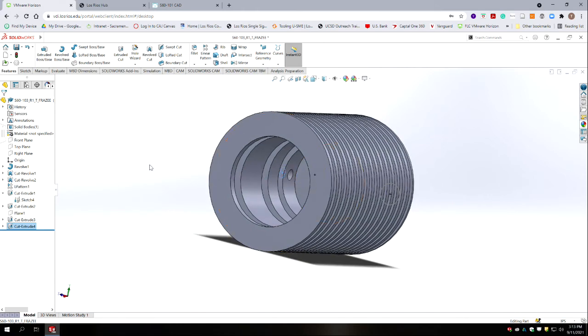That hole is just an air passage for air pressure to pass through. So as the large piston retracts, it's going to push pressure into the secondary piston, and it's going to push that one up. And then when it gets to the top of its cycle, gravity is going to help push it down, and the pressure coming back out of that cylinder is going to push the primary cylinder back into the test tube that's being heated. And then we have a compression cycle.